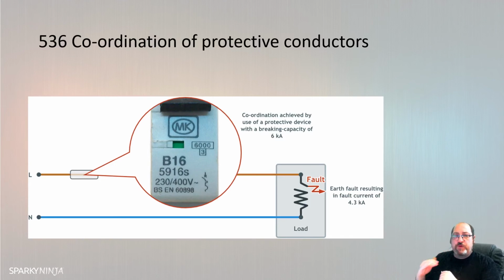Now if I had a fault such as a cable being drilled through or I was crushing a cable on circuits 21 or 22, it's likely that RCD1 would trip because there's no selectivity between them. You must ensure that there's selectivity in this case, and so an RCD at the origin or a distribution RCD, as you saw with the fire protection a minute ago, should really be of a type S, so of a time delay, so that there is a delay to allow a local RCD to operate.